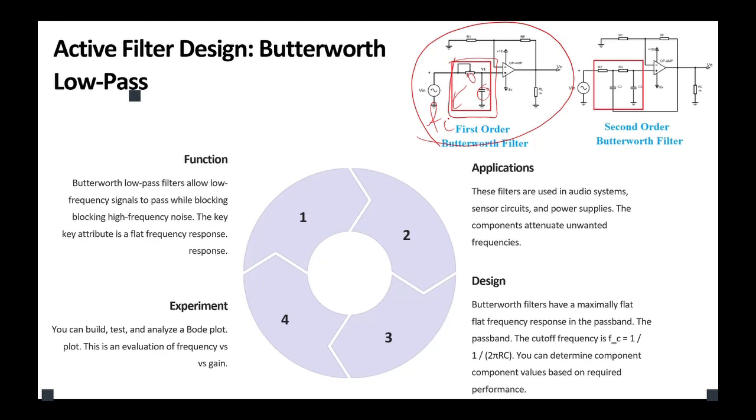So what is that cutoff frequency exactly? Let's talk about it. The cutoff frequency is the point where the filter starts to reduce the amplitude of the signal. So it's the edge of the passband. Everything below this frequency, when we talk about a low pass, passes through cleanly, and everything above that starts to fade.